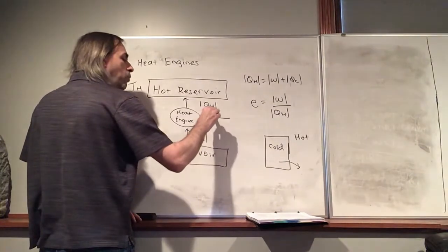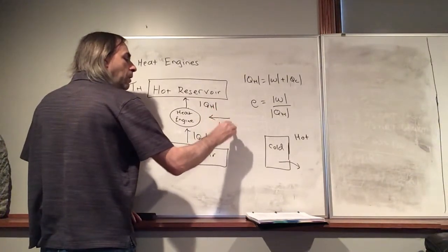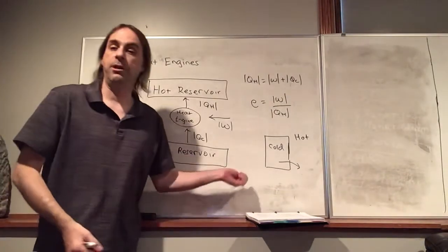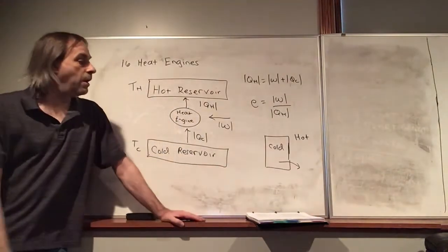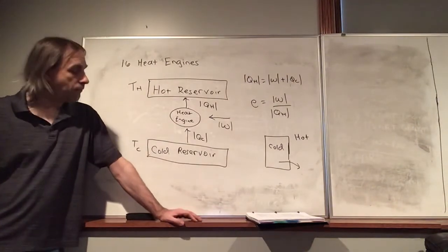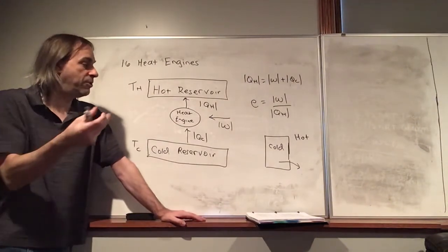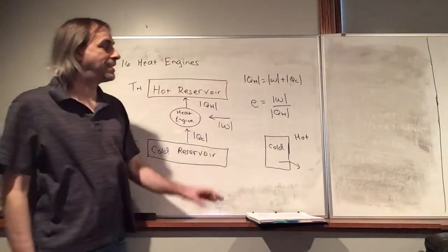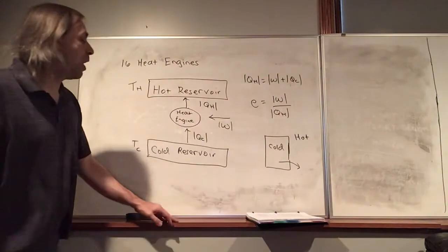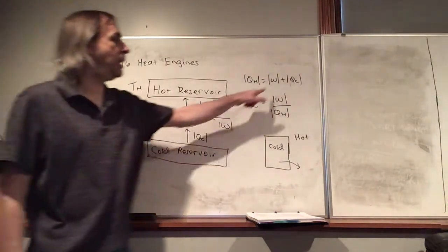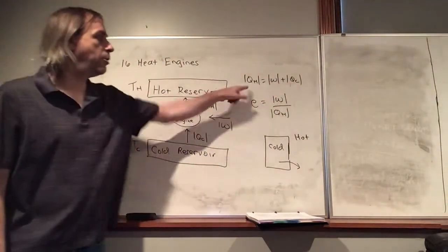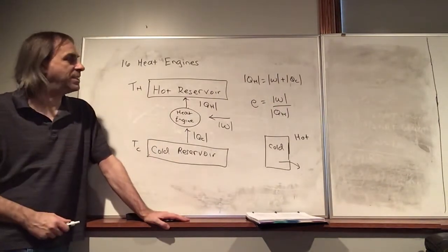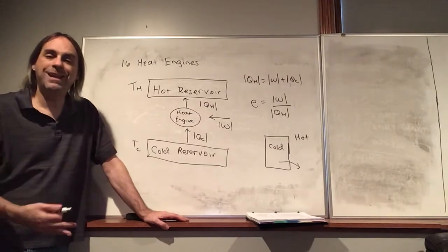And so we have to give it energy. We have to do work. Like on your refrigerator, obviously you plug it into an outlet, otherwise it's not going to work. So basically we just reverse these directions. But again, this equation is still valid. What goes in is W and QC. What comes out is QH. So heat engines and refrigerators work on the same principle.